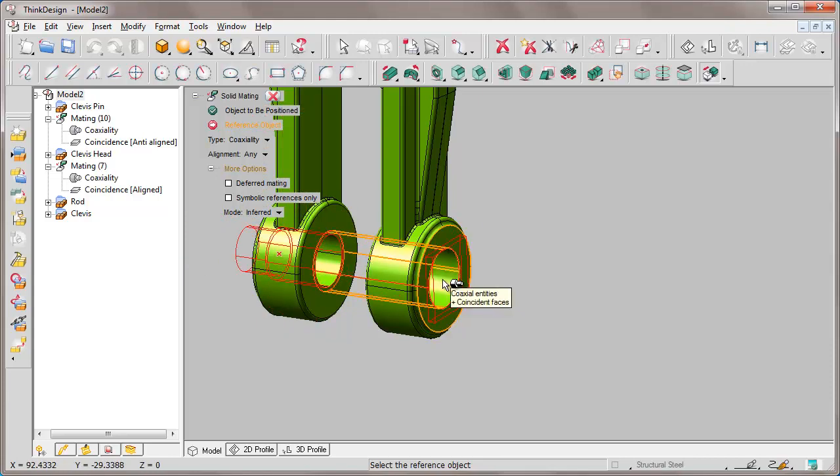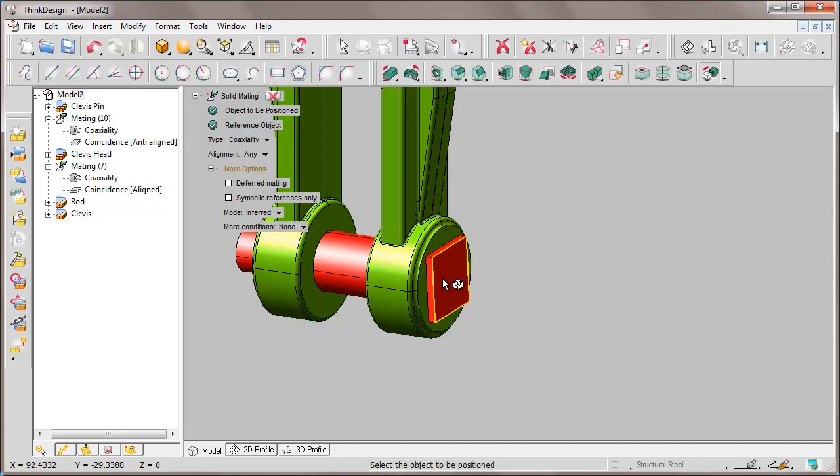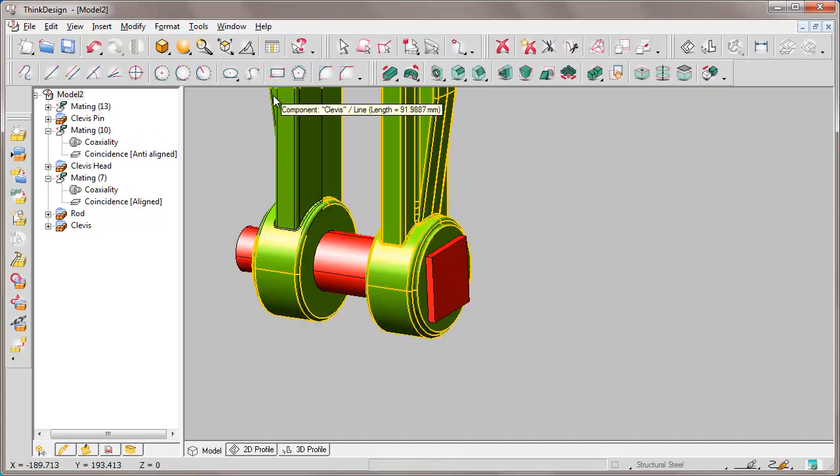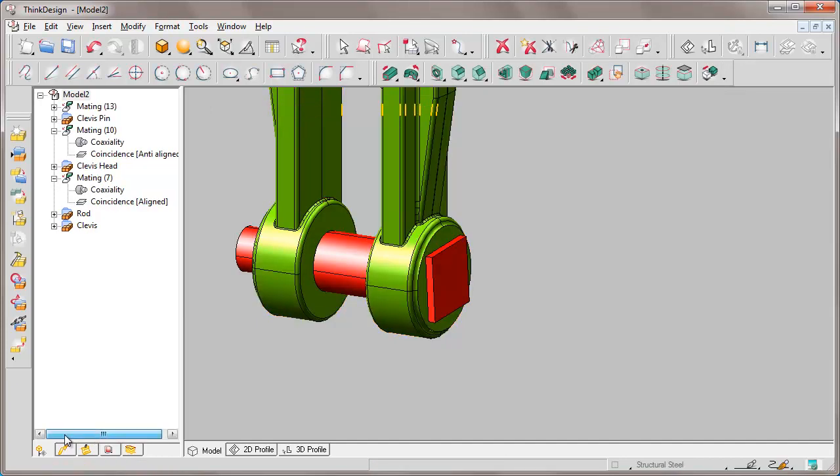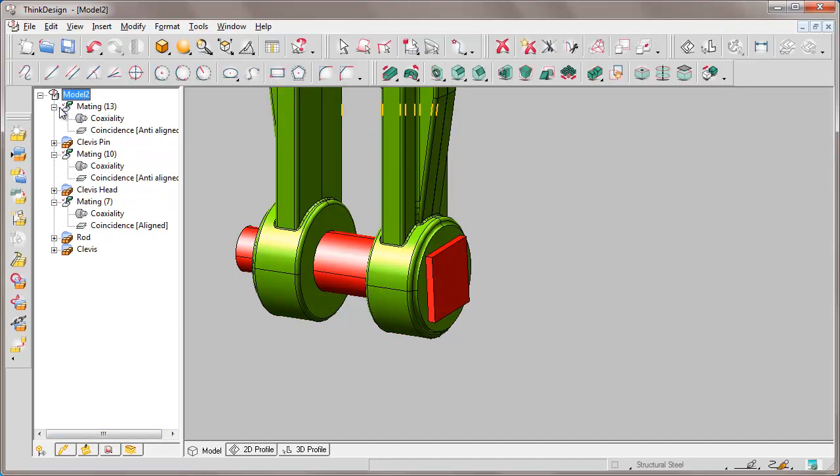OK. This is the bottom-up approach. We already have our components and use them to create the assembly, while with top-down, we build up each new component directly in the assembly file using other geometric elements and components already present.